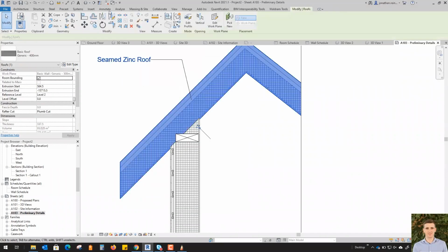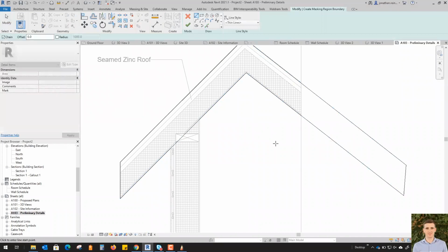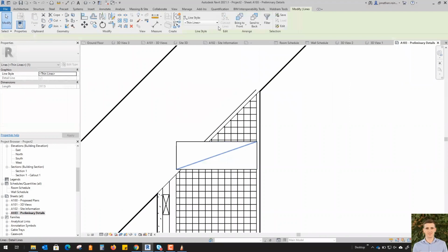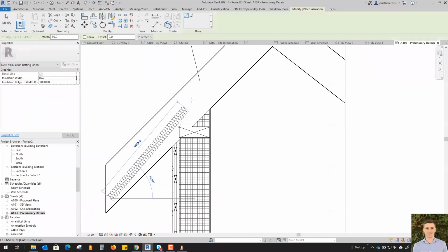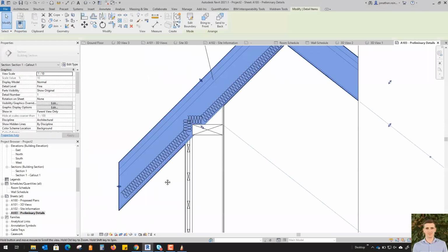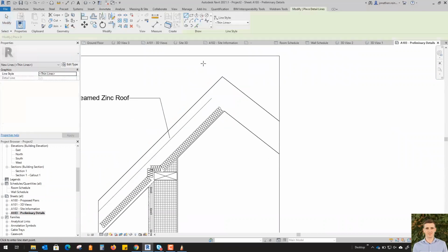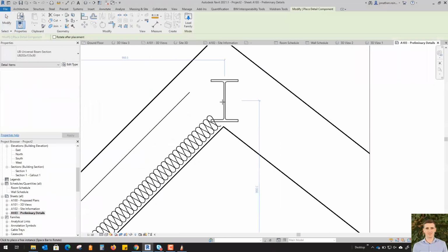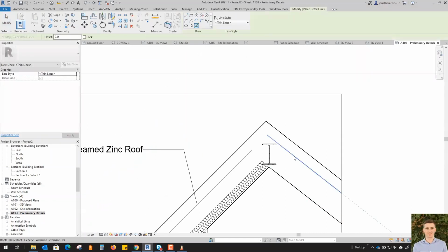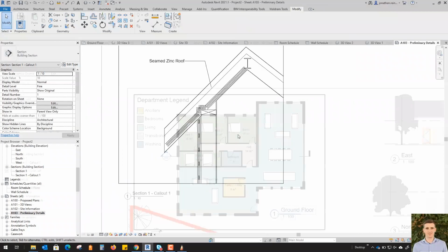And you can change the hatch types and everything, and even add in further insulation information, whether you've got membranes or air tightness seals, or any type of detail. Even if there's a bolt, for example, that you want to represent, that can all be done in 2D work. And for that reason, you can still focus on the 3D modeling elements, and then at the end of it, using your 2D detailing tools, still add in that important information at the construction stage as well.